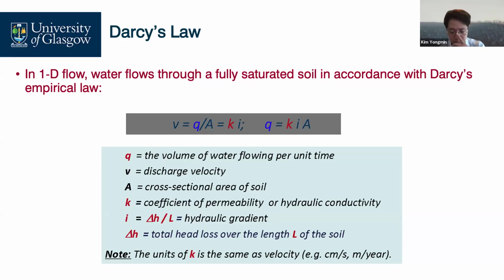Previously, I mentioned it is better to remember this equation. What is this? Se equals wGs. S is the degree of saturation, e is the void ratio, equals wGs. w is the water content, Gs is specific gravity, the relative weight compared to water. Se equals wGs. I'll give you one more equation I suggest you memorize.